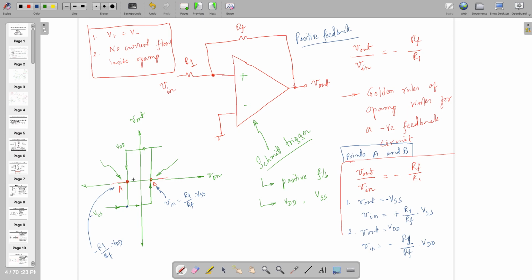We are going to use positive feedback as well as some sort of negative feedback having phase margin less than 45 degree, and other controlling criteria like the Barkhausen criteria we are going to implement so that the circuit acts as an oscillator. But right now our main aim is to make the circuit as an amplifier, not as oscillator.